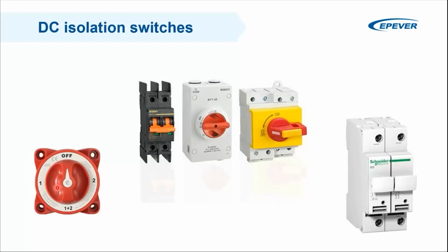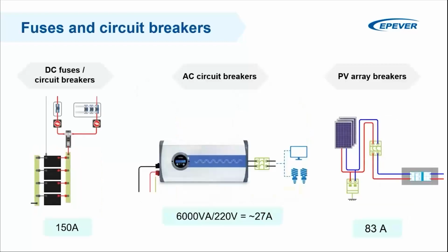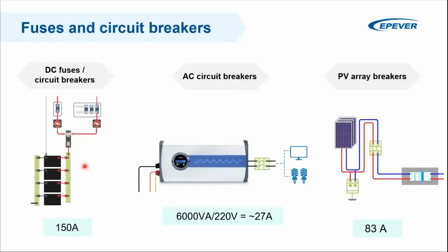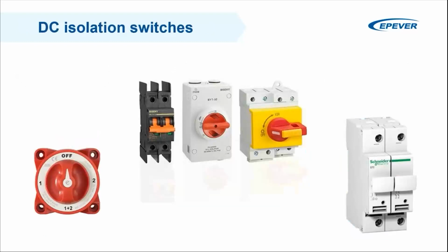So a battery isolation switch can be used to isolate the battery, as I mentioned. So if you disconnect the battery main fuse, one would argue that, okay, the fuse would do the same. Yes, that's true. If you just replace or disconnect the battery main fuse, then this is open circuit. But this is more nice, and this is more safe, and this is more easier to operate than just opening the fuse. But it depends on your preferences, really.